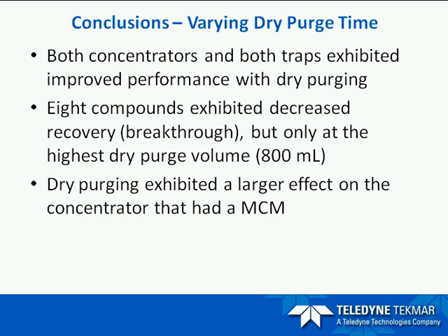Now, this slide summarizes the conclusions that were arrived at from the dry purge studies that we've just discussed. Most compounds benefit from the use of some dry purge. Now here at Tekmar, that's not surprising news to us. But again, for EPA, it's nice for them to investigate parameters that weren't previously mentioned in 524.2. Now they found that this is true even if that hydrophilic trap is in use without an additional moisture control system, or if a hydrophobic trap is configured with a moisture control device.